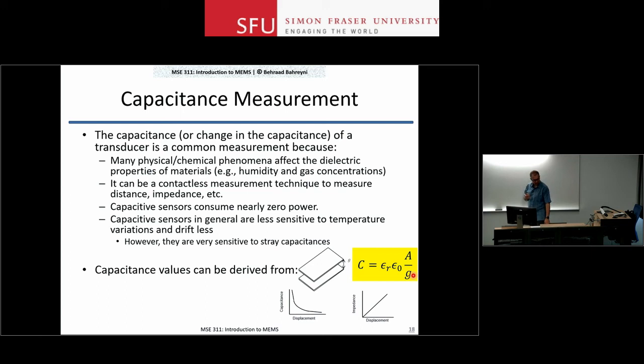You can measure capacitance from measuring the impedance of your capacitive device. Typically this requires you to produce an AC voltage. Basically, what you did for resistive measurements, this time with an AC source. So instead of using a DC source to produce a current and then measure a DC voltage, now you do it in AC, at high frequencies. If you know your device well enough and you can design your circuit to fit that device properly, this is doable.